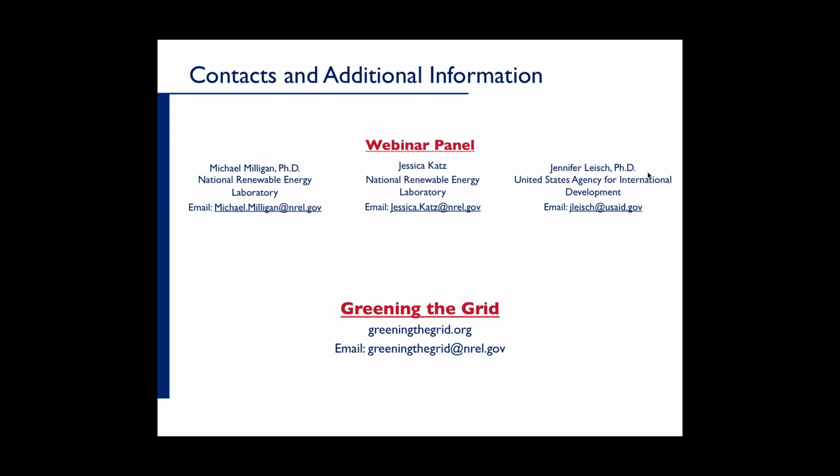As I mentioned earlier, wind turbines can respond to all kinds of signals. PV panels can also, but the question is, if I have 1,000 rooftop panels and I, as a system operator, need to reduce their output, what sort of equipment do I need to do that? There's got to be communication, there's got to be control, and how do I best do that as a system operator? So I think it's a great question. I don't have an answer much better than this, but I do think that the challenges really come down to visibility and potentially control, so that I understand from the operational point of view exactly what's going on.